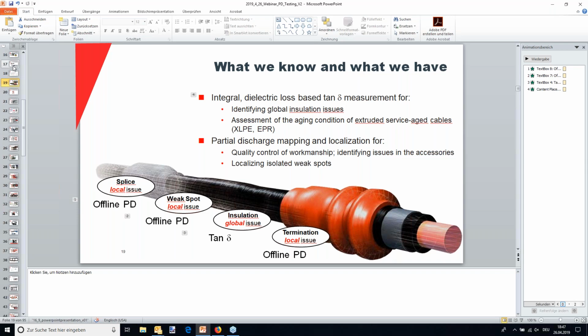Stay away from using dielectric materials, isolating materials, to shield nearby objects. Let's say you are in a confined space switchgear and you disconnect the termination and you bend it away to get some clearance. Do not put rubber mats over these other parts because that will make it worse. Why? Rule of thumb is if you have a sphere around your disconnected termination of 8 inches, 20 centimeters, the influence of the other grounded objects is minimized and you should not get too much corona.